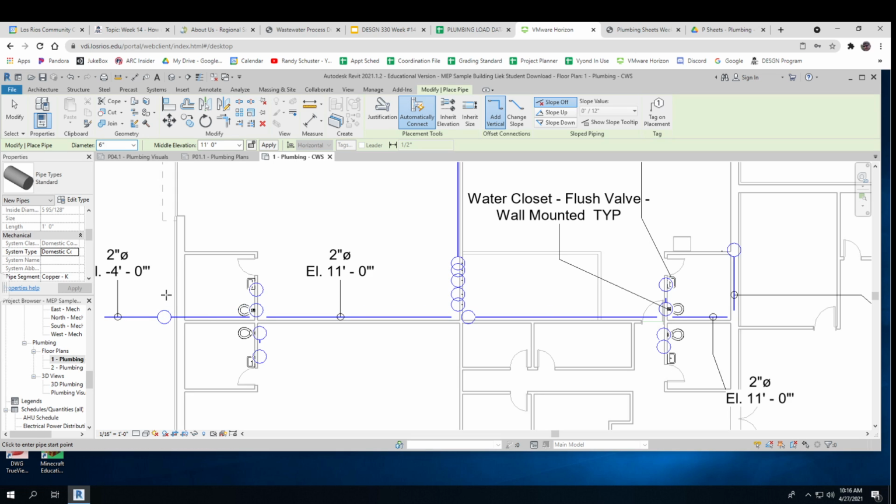So what some places do is they put a 40 or a 50 or a 60 degree water tank. It's not really hot, but it doesn't lose a lot of energy through convection to the air. And then this only has to increase 60 to 70 degrees instead of, if it's really cold outside, maybe even 90 to 100 degrees. So hot water for us is ignored, but usually it would be in there.